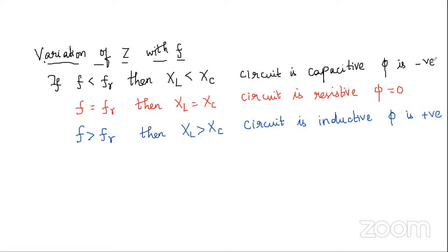So at resonance condition, usually the impedance of the resonance circuit is minimum. So it is called acceptor circuit. Okay. So in TV or radio sets, whenever we tune for a particular station, actually we adjust the resonance frequency. So when our resonance frequency is achieved, then the TV or radio is ready to receive the signals from a particular station. Okay. So all these things are important.